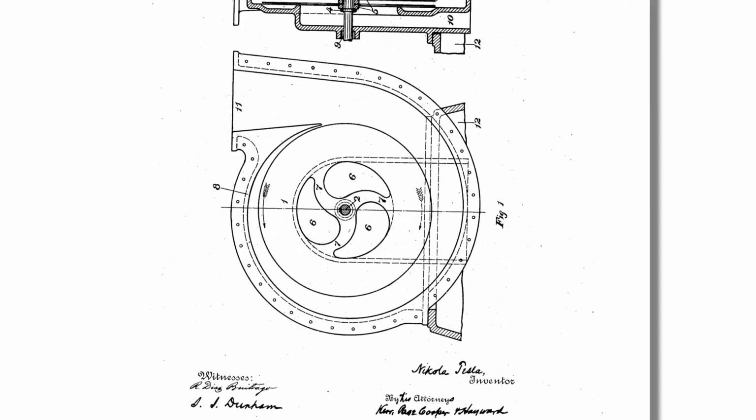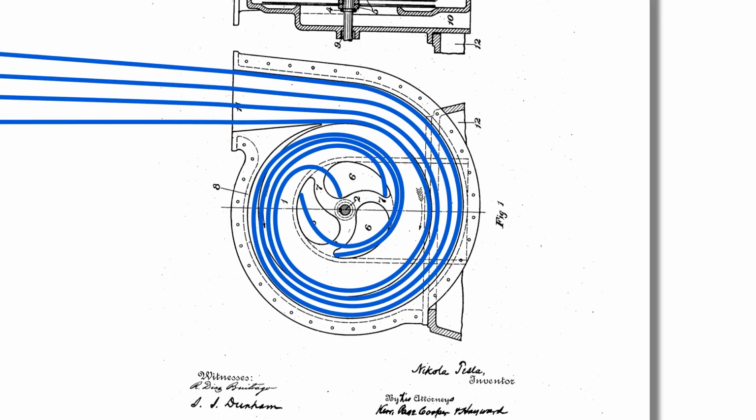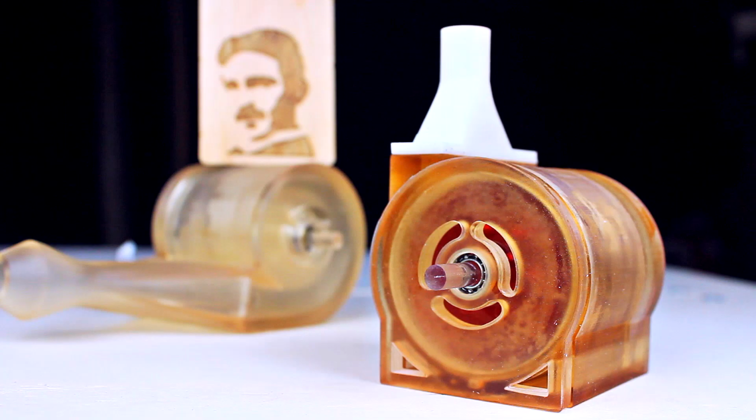I think the reason this design failed was the fact that the volute casing creates a big void at the outermost perimeter, exactly where the flow is more laminar and efficient. The flow goes towards the center in a more gradual way, but at the cost of making the disc smaller in comparison with the diameter of the casing. So for now the standard design still wins.